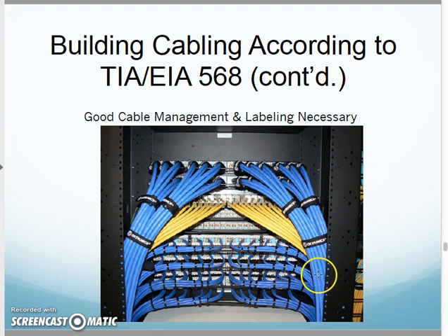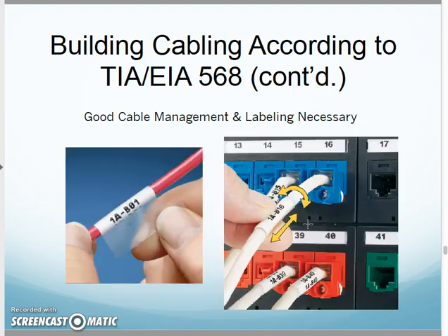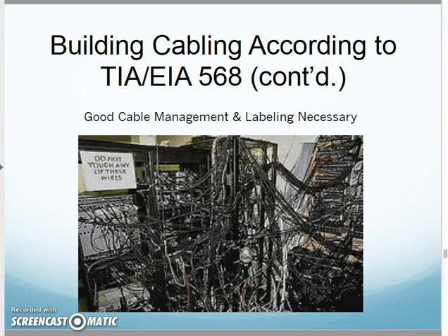That way it's nice and organized. There's no stress on the terminations or connections. Troubleshooting becomes easy. Along with that, reminder, don't forget cable labels. Good cable labeling on the cables, patch cables, horizontal cables, everything. That aids with troubleshooting and tracing through problems.